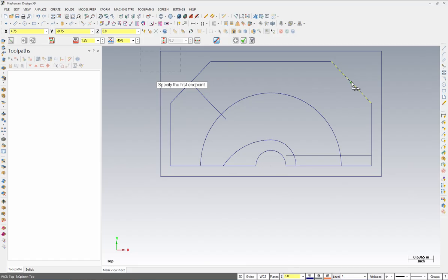Select the midpoint, sketch it, change the distance to 1.25, hit enter on your keyboard, and change the angle to 270 minus 45 degrees and hit enter on your keyboard. When this is done, select OK. Your part should look as shown.